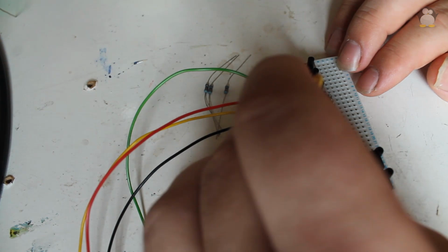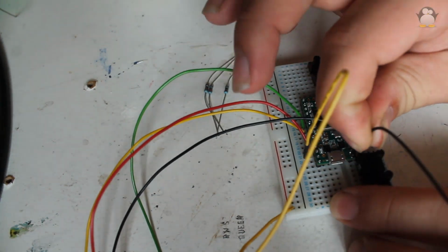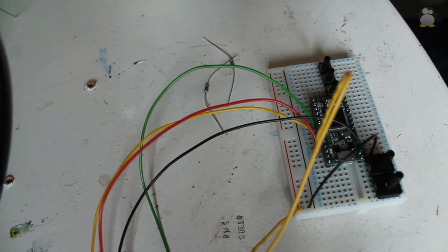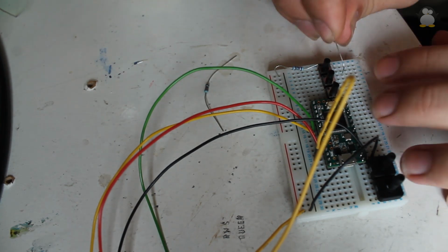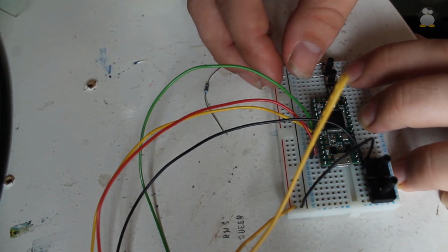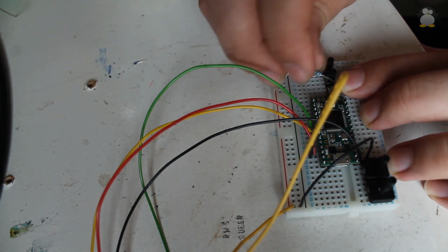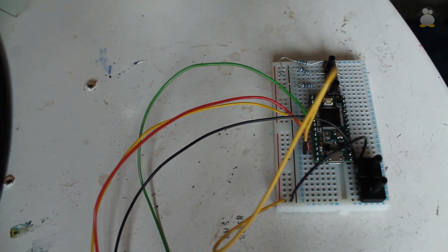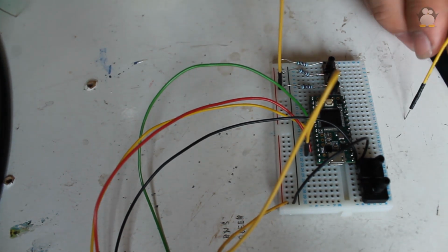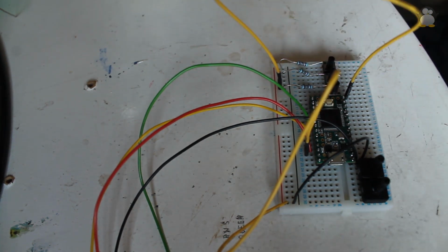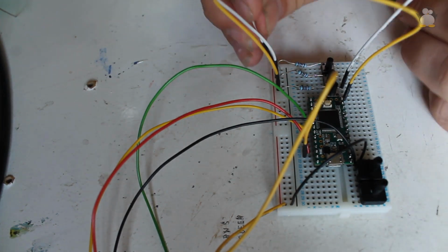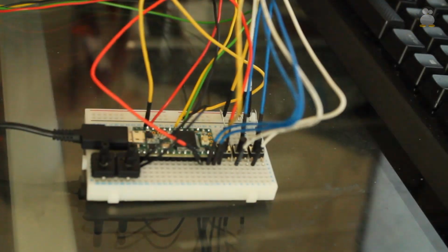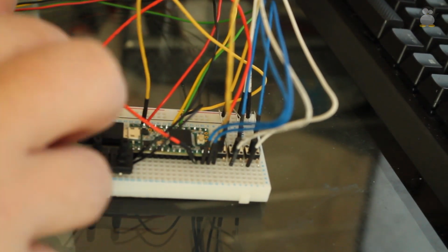Now that we've got that, it's time to wire in the rest of our hardware. First I'm creating a power rail and a ground rail on the top of our breadboard. Then I'm connecting one side of our buttons to ground through a resistor. Each resistor is a 10 kilo ohm resistor. Once I've done that, I'm going to connect the other side of the button to power. It's not shown in this video, but after having done this, I connect the top left-hand pin of the button to the corresponding pins on the Teensy, as you can see it's shown here.